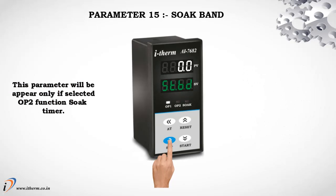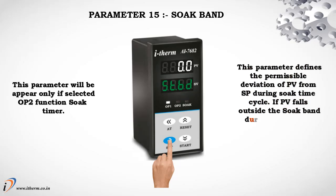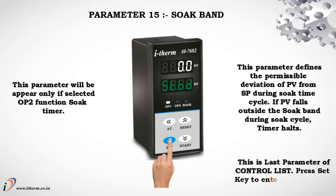Parameter 15, Soak Band. This parameter will appear only if selected output 2 function is soak timer. This parameter defines the permissible deviation of process value from set point during soak time cycle. If process value falls outside the soak band during soak cycle, timer halts. This is the last parameter of control list. Press Set key to enter in run mode.